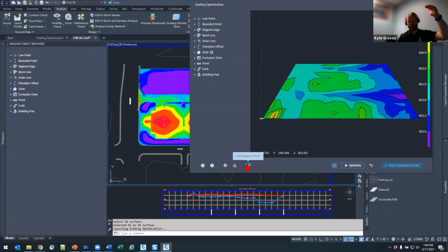So you've got your 10,000 iterations, or your maximum number of iterations, on the top, and you've got 1 on the bottom of that. As that line comes closer and closer to being 1, stable, and to the bottom of that graph, it's getting to what it thinks is a really good design. So your convergence plot is going to level out and get very far down on your graph. That is how you're going to know when you're close.